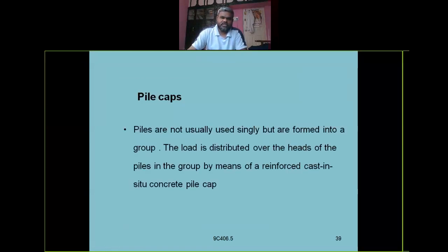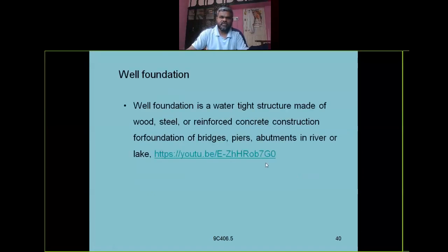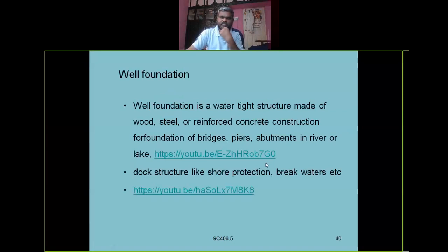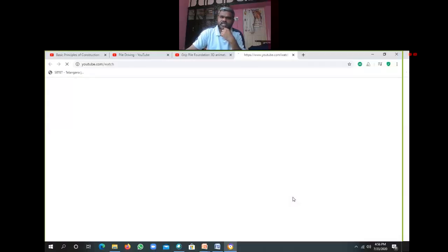And pile caps. Piles are not usually used single, but are formed into a group. So, group of driven piles. The load is distributed over the heads of the piles in the group by means of a reinforced cast in situ concrete pile cap. Right. So, next well foundation. Well foundation is a watertight structure made of wood, steel.